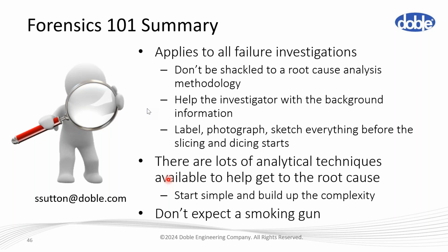So another two questions related to PD, partial discharge. Usually once the cable's in service, normally PD testing is done from the ends of the circuit, from the terminations, particularly for medium voltage cables. You can see probably up to about 4 kilometers down the cable and still detect partial discharge up to 4 kilometers away. So for medium voltage cables, generally testing at either end of the circuit, you will see those discharges all the way along the route.